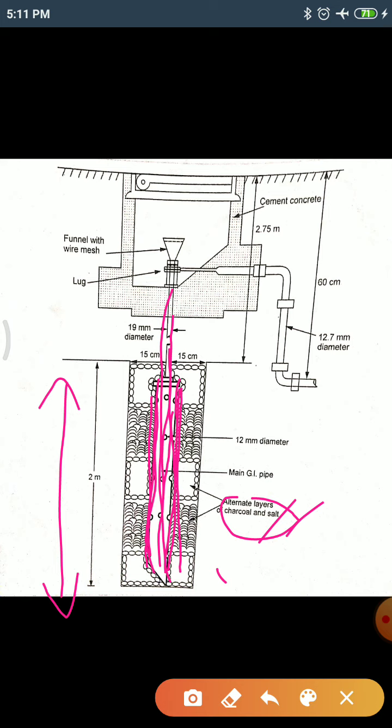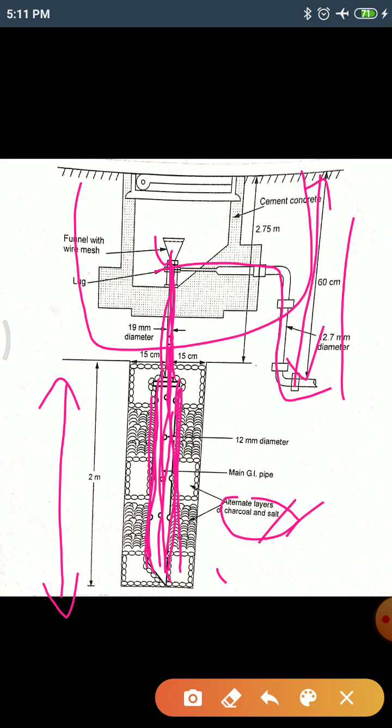Similarly, as in plate earthing, this is also provided with a funnel on the outside. This is the construction outside. Then the earthing wire has to be taken from this, again 60 centimeter below the earth. Since the earthing wire is taken from the upward direction where a funnel is there, you can check manually and regularly whether the earthing wire has touched earth or not.